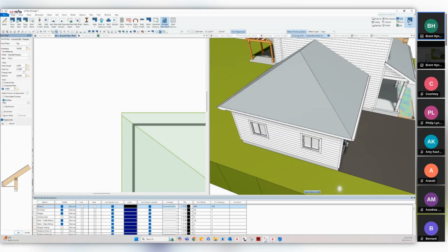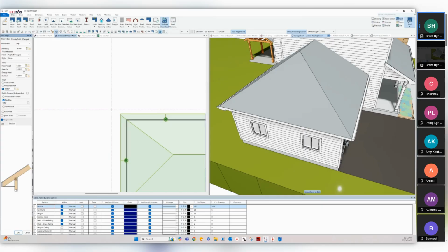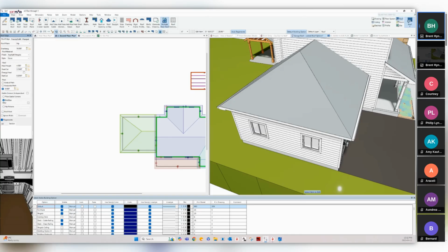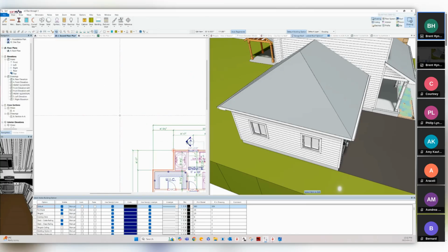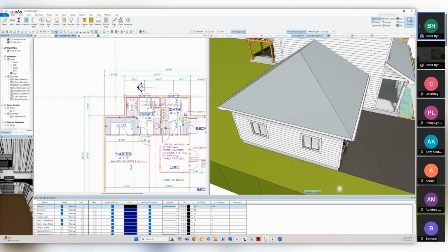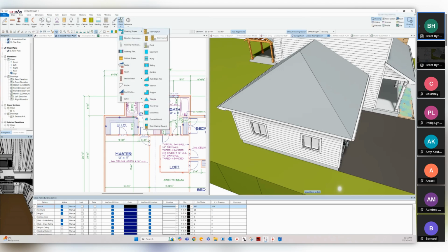Okay. So just an illustration as to how that's going to work. All right, second item we want to take a look at is the door layout tool. So I'm going to just zoom us back out a little bit to some open space here. I'm going to flip this back over to drawing mode. In drawing mode, for those of you who have worked with elevation openings in the past, this is just an added tool that makes it much more robust. So we're going to go to draw, detail, opening shapes, and in there you're going to see door layout.